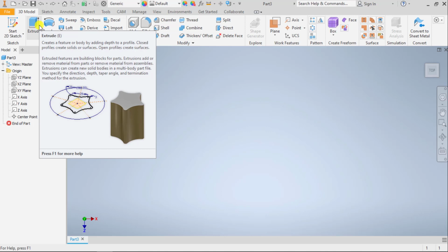Rectangles work the same way. Polygons also work the same way. When we covered polygons under sketch geometry creation, those are by default closed. Where you can get into trouble is when you are drawing things by hand and you're clicking endpoints and something just doesn't line up quite right. A constraint isn't put in.